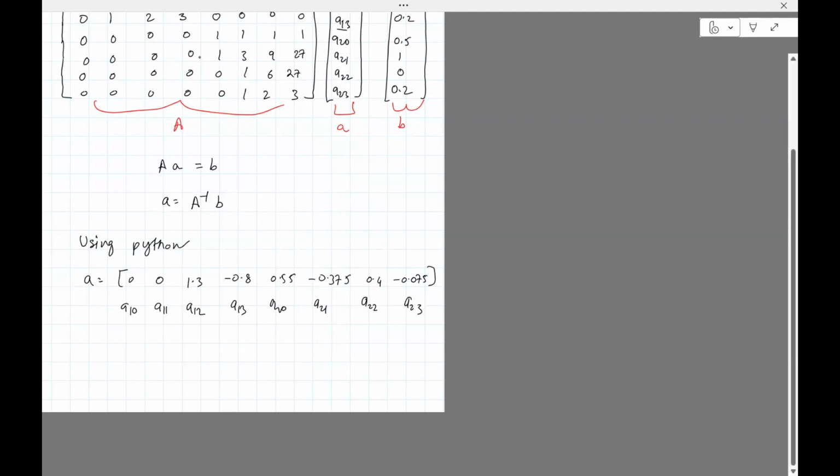Okay, so once we've got the coefficients, we've pretty much got the curve, because theta1, remember, is A10 plus A11 t plus A12 t squared plus A13 t cubed, and theta2 of t is A20 plus A21 t plus A22 t squared plus A23 t cubed. So we've got the a's, and we've got basically the function of time. Okay, so what does this look like?